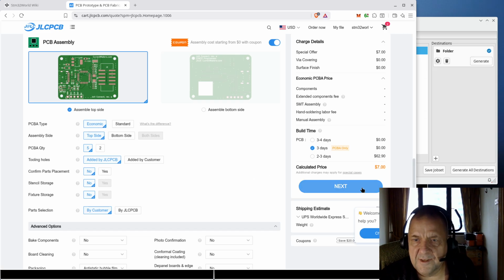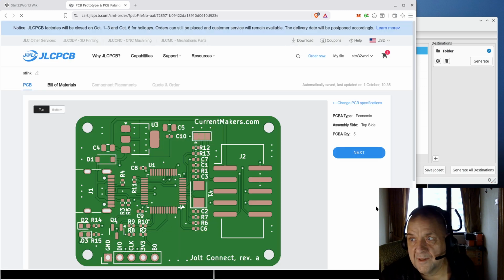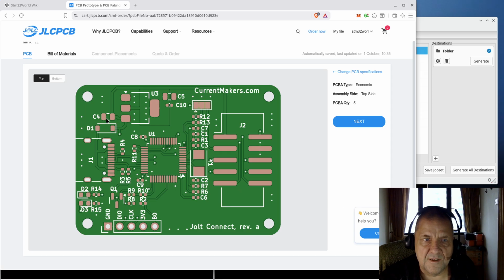So you click next. Now this page, I always stop and think. I mentioned earlier that a couple of times I have forgotten to add the drill files. That will be obvious here, that all the wires and all the holes are not drilled. So time to check that this one looks reasonable, but I've already checked that. So let me move on.